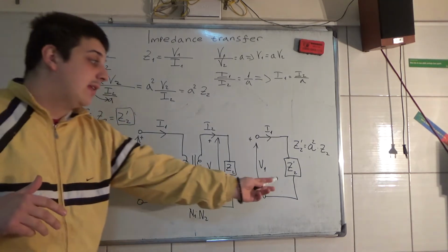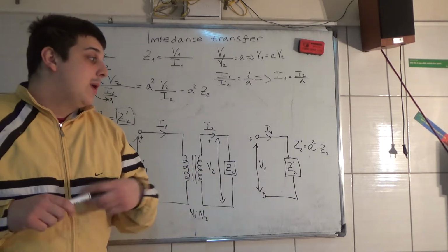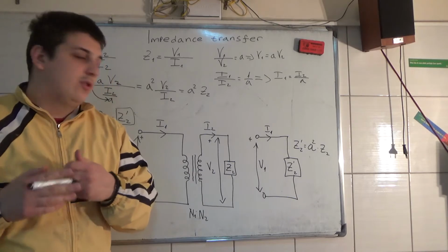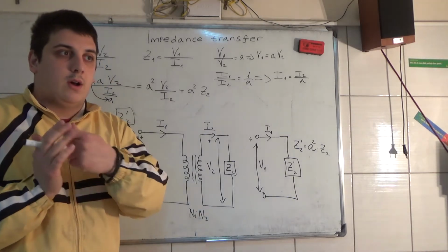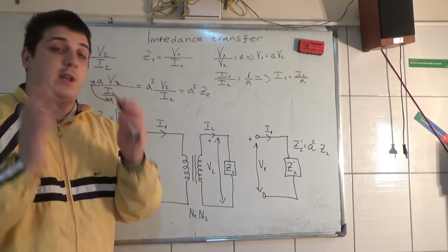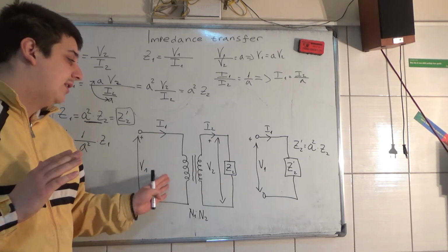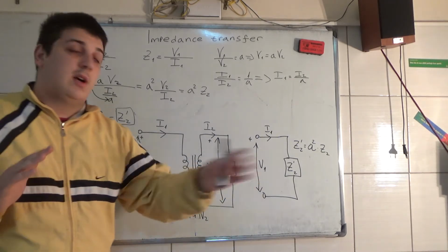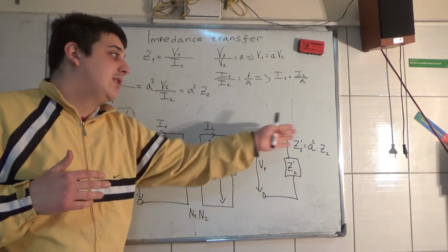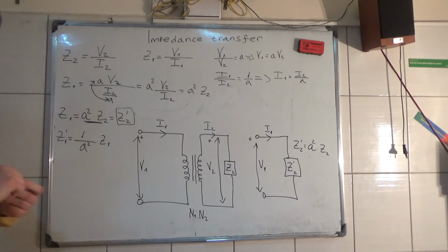And then we get this kind of schematic over here. Why do we do this? Well, because it is easier to calculate all the parameters, voltages, induced voltages, the power, in only one circuit, not like this. So we don't use these circuits. It's very useful for us to do these transformations from the secondary to the primary.